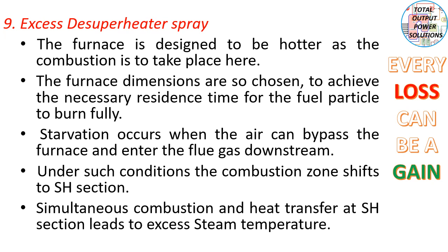Excess de-superheater spray. The furnace is designed to be hotter as the combustion is to take place here. The furnace dimensions are so chosen to achieve the necessary residence time for the fuel particle to burn fully. Starvation occurs when the air can bypass the furnace and enter the flue gas downstream. Under such conditions, the combustion zone shifts to the superheater section. Simultaneous combustion and heat transfer at the superheater section leads to excess steam temperature.